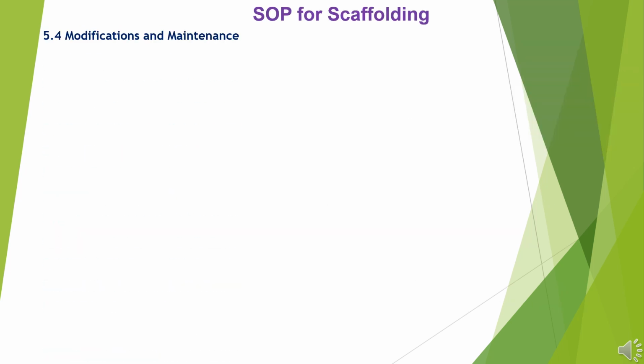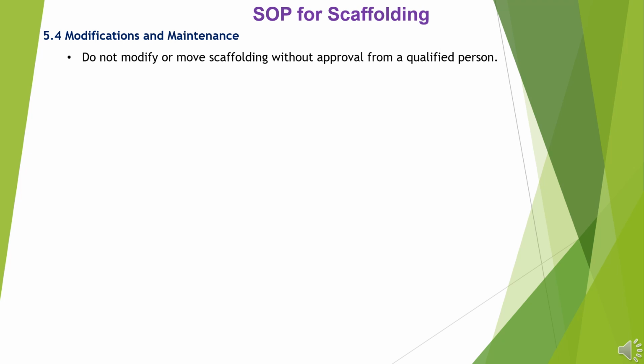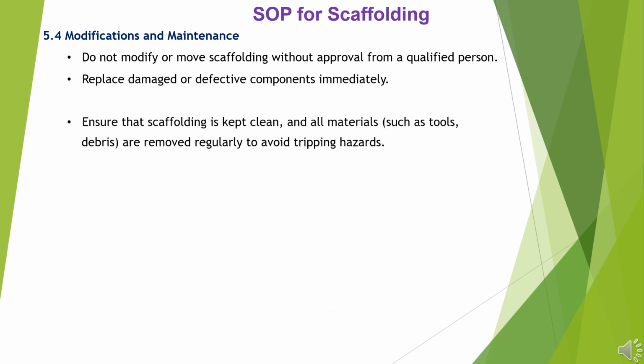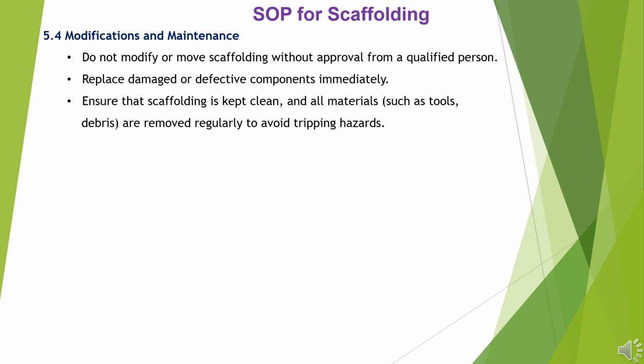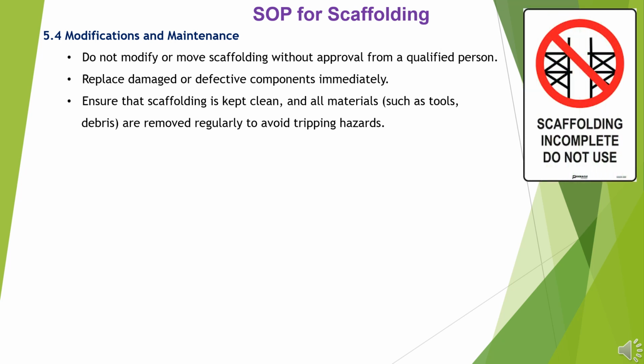Modifications and maintenance. Do not modify or move scaffolding without approval from a qualified person. Replace damaged or defective components immediately. Ensure that scaffolding is kept clean, and all materials, such as tools and debris, are removed regularly to avoid tripping hazards.